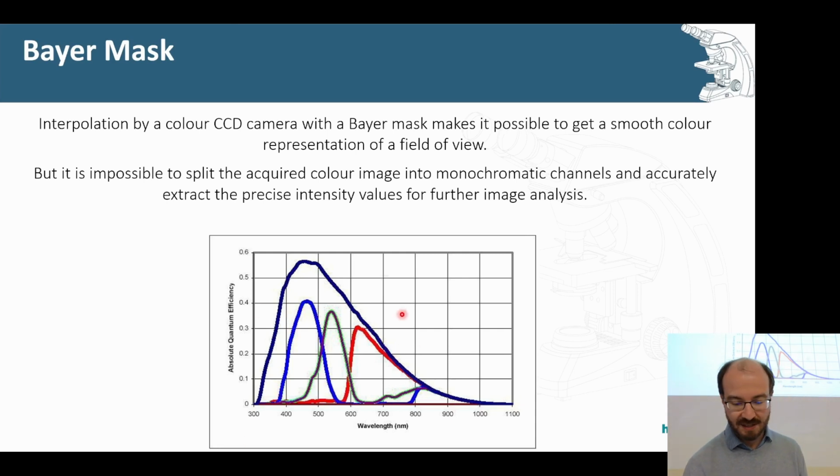So if I want to capture this entire spectrum, I end up capturing some portion in the red, which corresponds to this range of wavelengths. I capture some portion in the green, which corresponds to this spread, and then the red also in the latter part. But what this implies is that I can't ever get the true representation of the signal out, because all of this entire intensity where this photo element is sensitive is going to be combined into a single value, say 205 intensity.